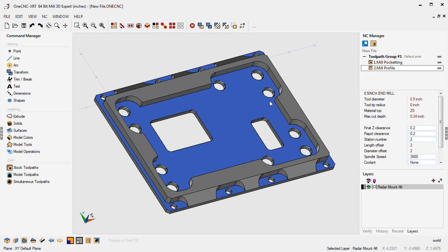Okay, so when calculating your feed rates, what do you take into account? Well, typically you take into account things like depth of cut, the material, the type of tool, chip load, all those are big factors. But some other factors you should be considering are things like abrupt toolpath direction changes and also small fillets. Let me give you an example.